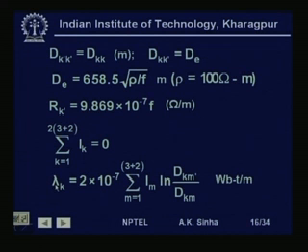Now, for such a system, we can find the flux linkage for any conductor very easily, and lambda k in this case is given by 2 into 10 to the power minus 7, sigma m equal to 1 to 3 plus 2, that is 3 phase conductors plus 2 ground conductors, I m log n d k m dash, that is the distance from the conductor to the image conductors, divided by d k m, the distance between 2 overhead conductors, and these include the ground conductors as well.